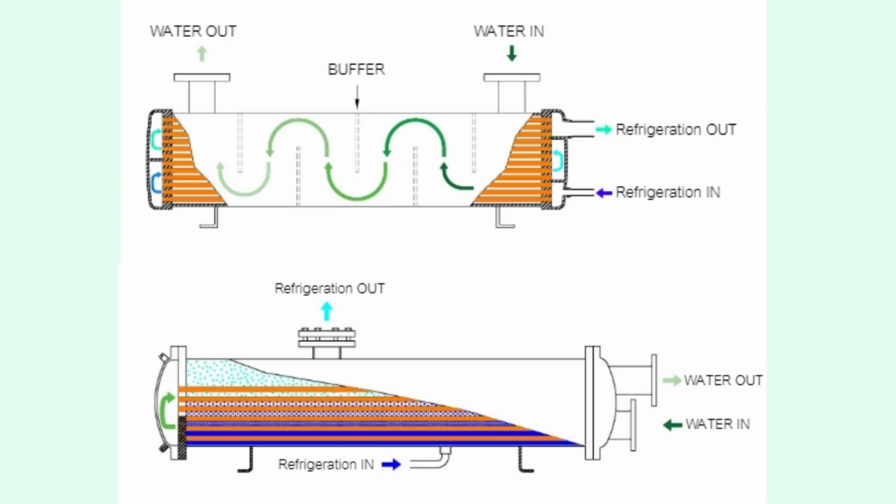The efficiency of this process is defined by the approach temperature, the temperature difference between refrigerant and leaving water temperature. A smaller approach means better heat transfer. Flow rate is critical. Too high flow means erosion, vibration, noise, and control instability. Too low flow means laminar flow, poor heat transfer, and chiller trips on low temperature. Chiller manufacturers specify minimum, maximum, and allowable flow variation rates, often plus 10% per minute for standard controls, up to plus 50% for advanced systems.